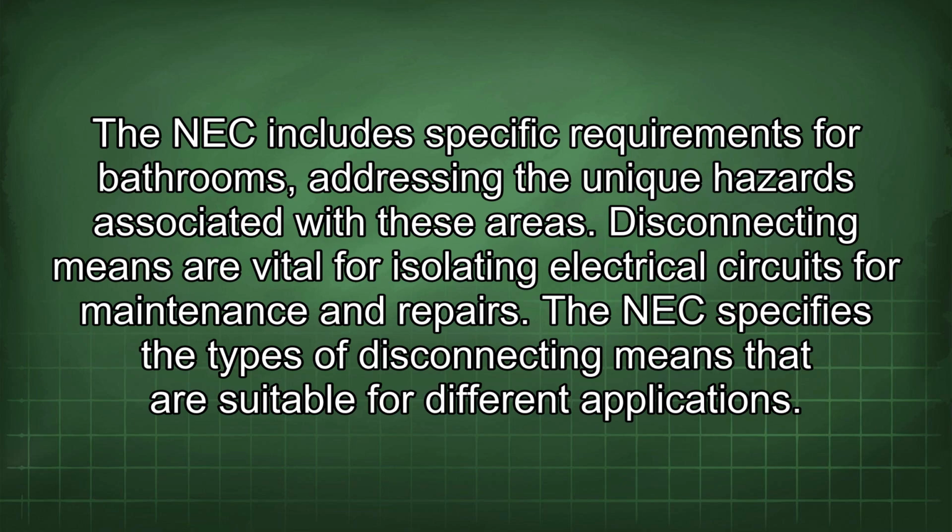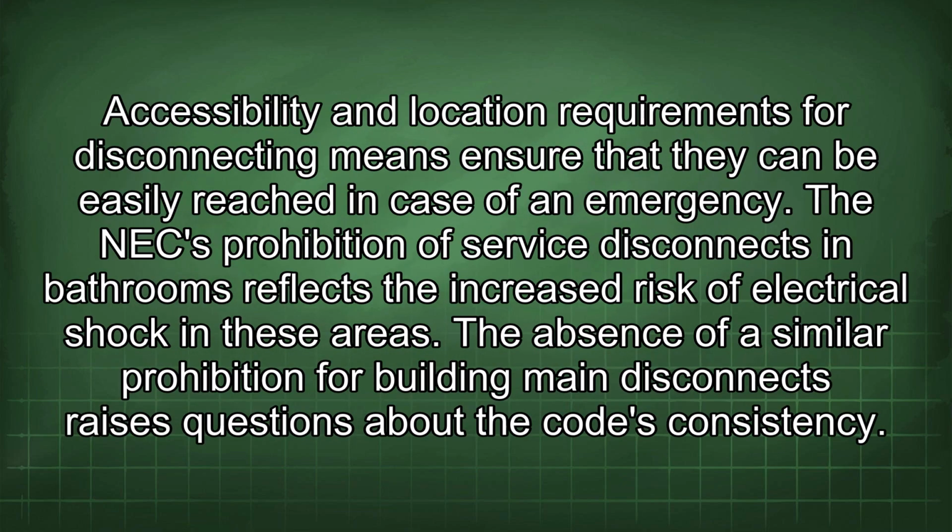The NEC includes specific requirements for bathrooms, addressing the unique hazards associated with these areas. Disconnecting means are vital for isolating electrical circuits for maintenance and repairs. The NEC specifies the types of disconnecting means that are suitable for different applications. Accessibility and location requirements for disconnecting means ensure that they can be easily reached in case of an emergency. The NEC prohibition of service disconnects in bathrooms reflects the increased risk of electrical shock in these areas.